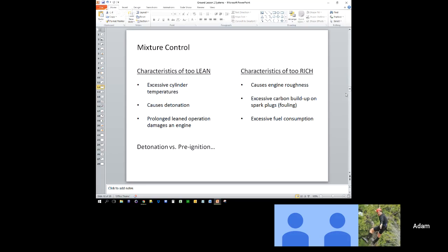And from the pilot's perspective, it's always important, as you're doing cross-country flights, cruising at 3,000 during the first hour, then 6,000 during the second and then 12,000 during the third hour, to keep an eye on your mixture, because there are consequences to operating the aircraft at the wrong mixture setting.